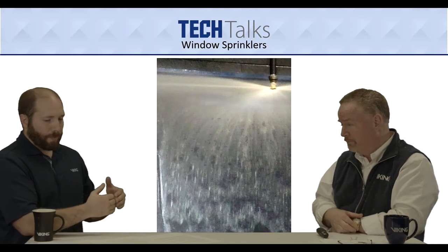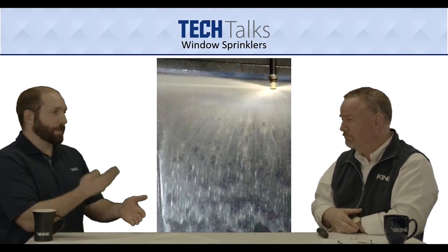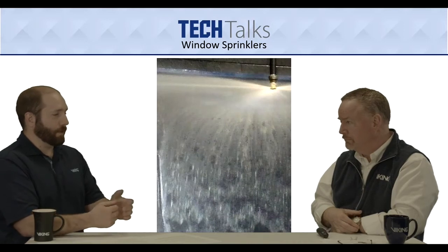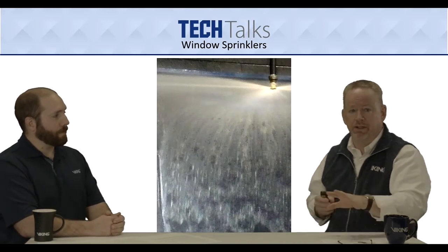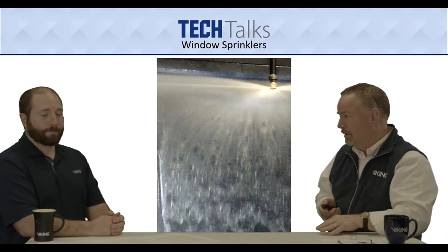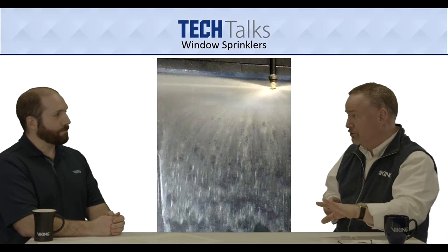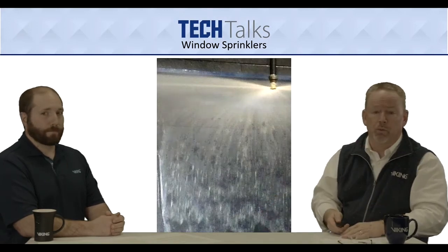Absolutely. We're not really trying to put the fire out with the window sprinkler. We're trying to contain it so that the sprinklers in the room can take care of the fire in the room. Right. So we're maintaining the tenability of the space with that particular sprinkler, maintaining the fire resistance rating of the window.